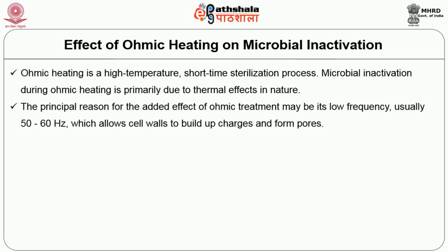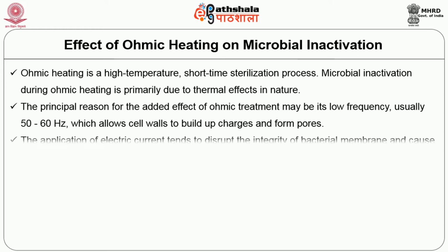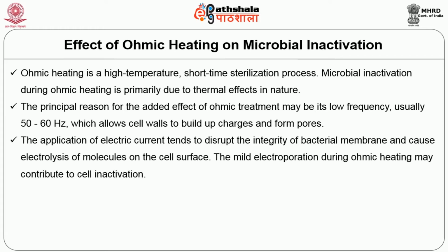The principal reason for this added effect of ohmic treatment may be its low frequency, usually 50 to 60 Hz, which allows the cell wall to build up charges and form pores. The application of electric current tends to disturb the integrity of the bacterial membrane and cause electrolysis of molecules on the cell surface. The mild electroporation during ohmic heating may contribute to the cell inactivation.